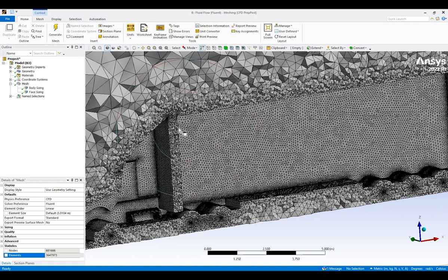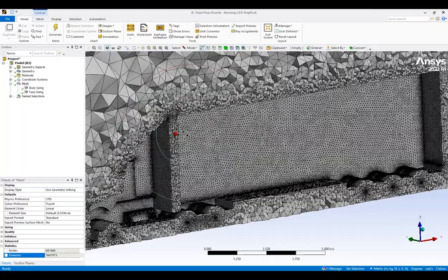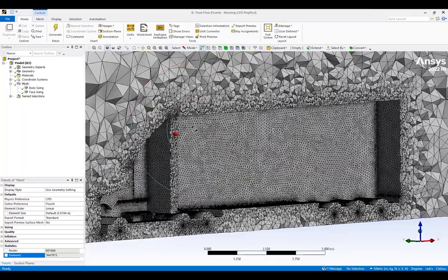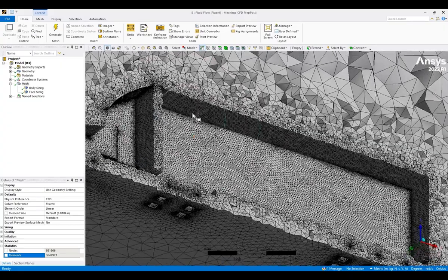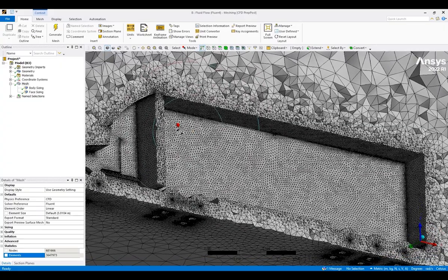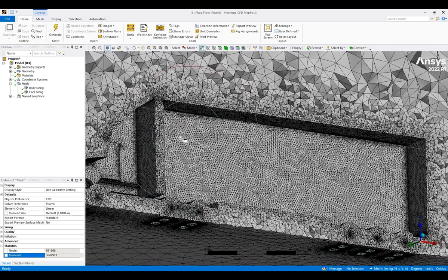So I'm gonna actually leave it up to you as an exercise, so that you can perform the steps of simulation again and see whether the current mesh is good enough for the simulation using the SST k-omega model or not. If not, you're gonna have to come back again and make the mesh cells on the surface of the truck smaller again, and then perform the simulation again until you get the correct value of the y plus.